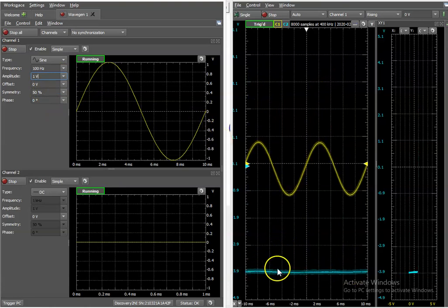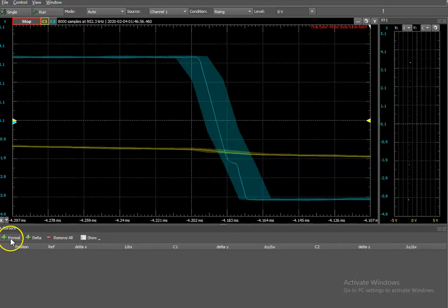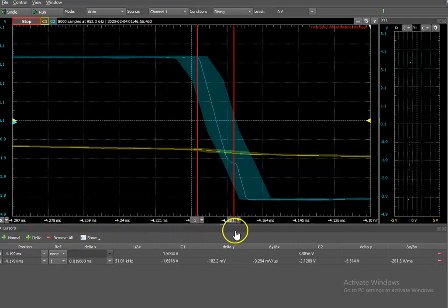In this experiment it is also possible to measure the slew rate of the op-amp. From view option, place 2 X cursors as shown in the scope. And observe the slope of the output waveform. And note down the value. This way we can conduct the many combinations of non-inverting Schmitt trigger using op-amp.